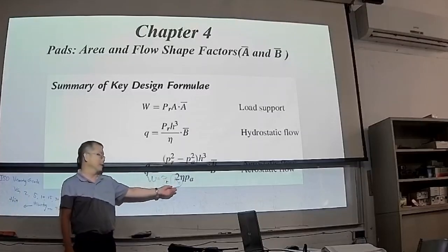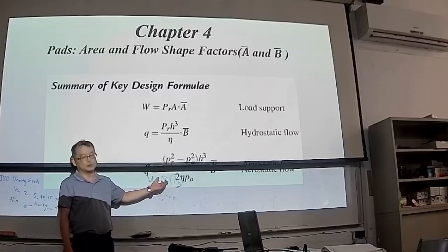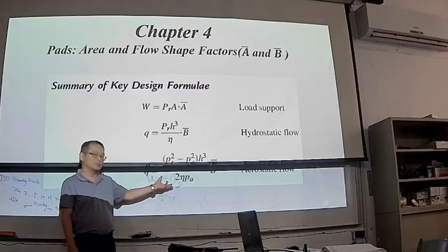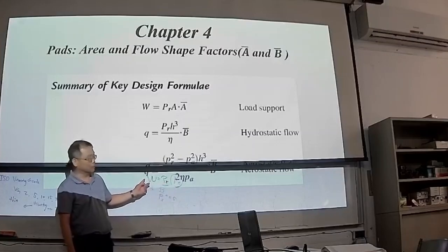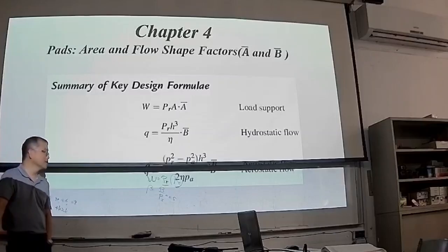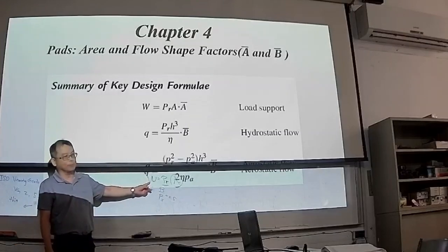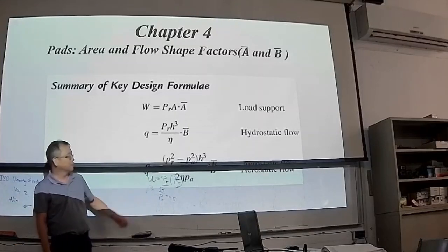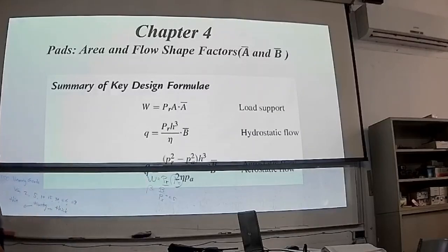Each bearing pad area you can calculate, and then with the recess ratio, you multiply by 4 and you have the total load capacity. For example, for the slide table with 4 pads, what is the maximum load capacity for this hydrostatic bearing? So in this chapter, you will know how to calculate or estimate the bearing pad.